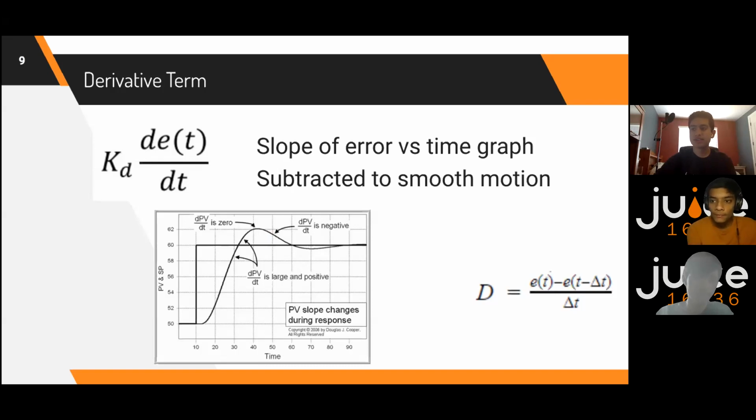Yeah, because the thing is when you tune just the proportional and integral portion, it's far easier than managing 3 different variables, because if you increase KD, you might then start not reaching your target. If you decrease KD, you might overshoot, and then it's too many variables to take into consideration, and it'll exponentially increase your tuning time. So we found that it's not necessarily worth it to introduce the derivative term, but you can if you have the time or if you feel the need to introduce it.